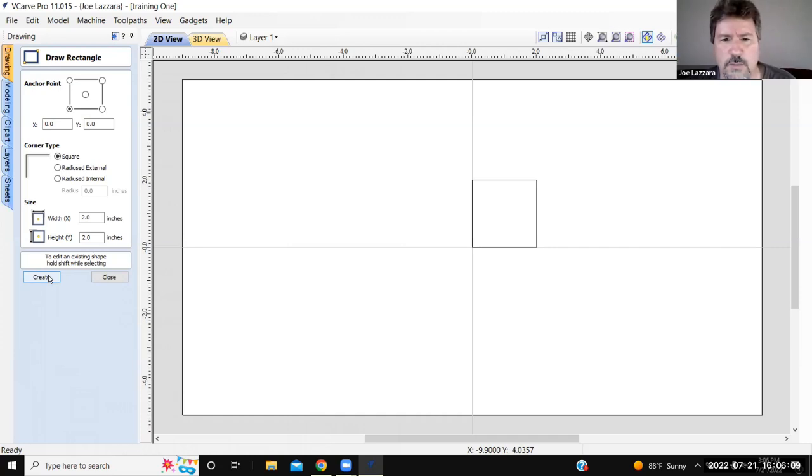Huh. Okay, so what you just did is you're telling it to make a 2 inch by 2 inch rectangle, right? It's all started on 0, which is right here. And by clicking that lower left button, you're telling it that the rectangle is going to start from this corner and build out. Notice that the rectangle is built out that way. Yeah. The little blue button is going out that way as well. Yep. Okay, now click the Control Z.